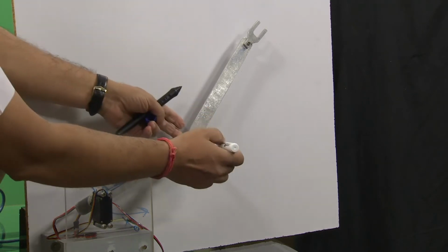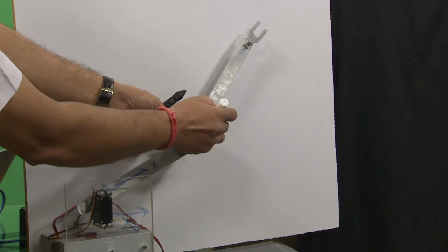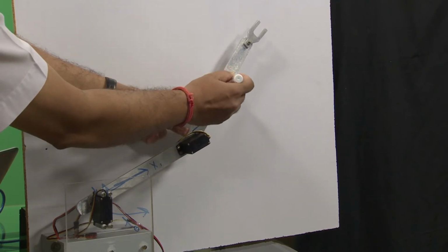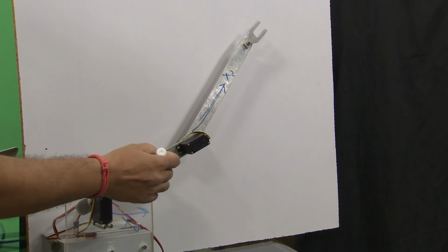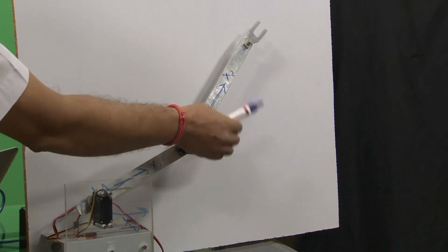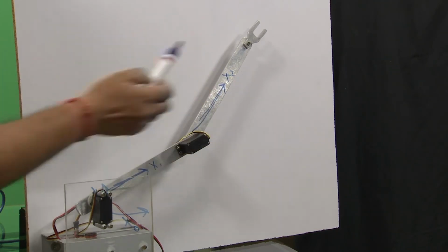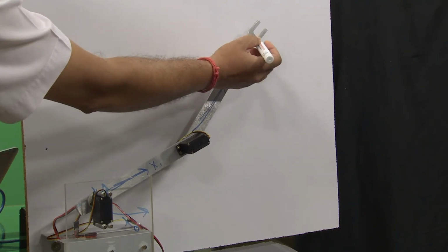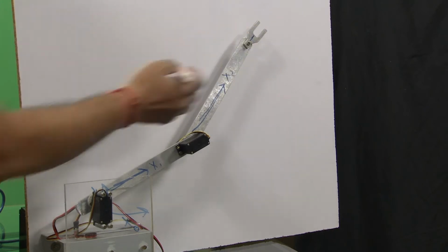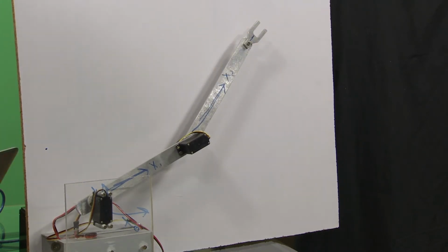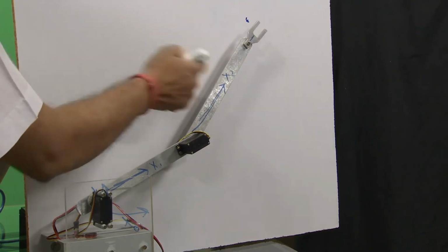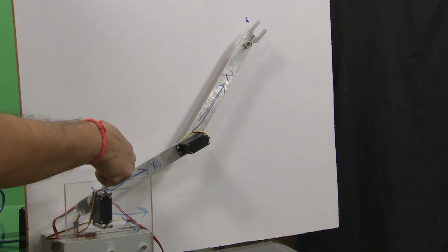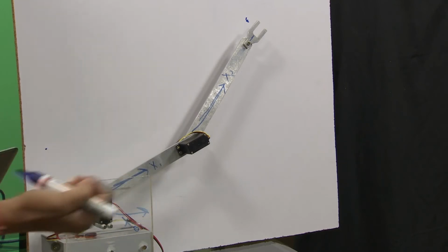Now if I assign another axis here, the z is coming outward, and I assign an x2 here, then this is my x2 axis on the link. Then there is an angle between the x1 axis which is like this and the x2 axis which is there, that is my link variable theta2. And I can assign a third axis here and call it the x3 axis, and the z3 axis is like this. So essentially this means that if I want to go to some point in space, I will need to know the relationship between this frame and this frame, and then this frame and this frame, and then the frame 1 with respect to the frame 0.